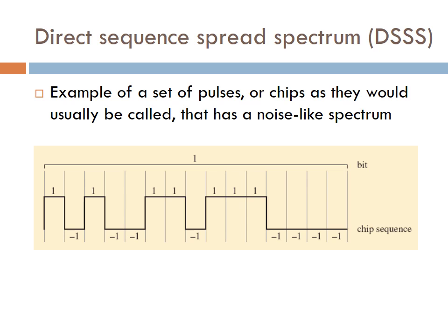Practical spreading codes often have many more digits than I have just used in this example. The idea with DSSS is to use a sequence of chips such as that to represent a 1 in the data to be transmitted. Every 1 in the data would be represented by the same code. Every 0 would be represented by another code, usually the inverse of the code used to represent 1. All the 1 chips would become -1, and vice versa.